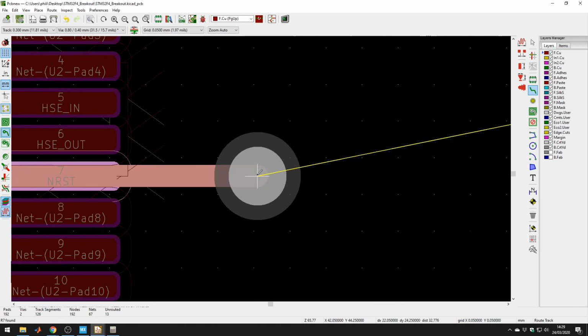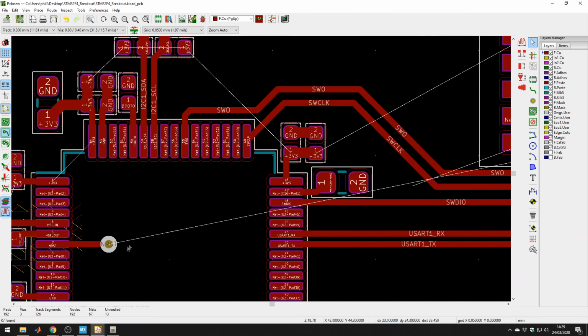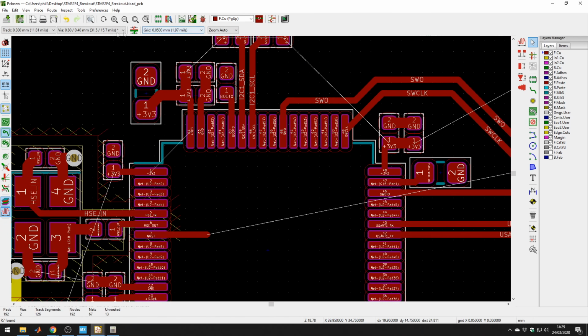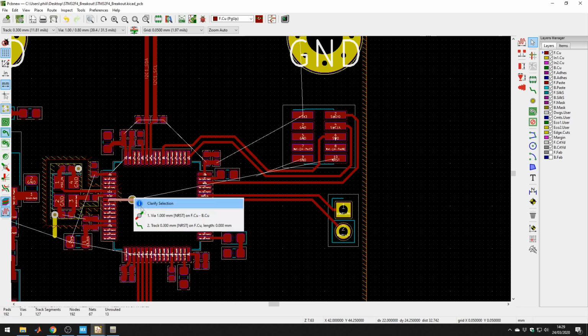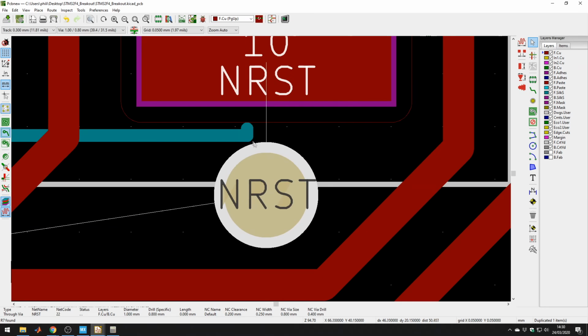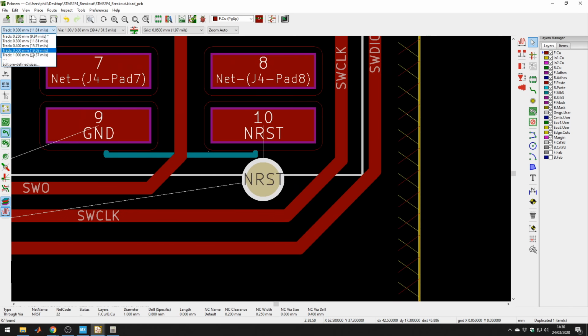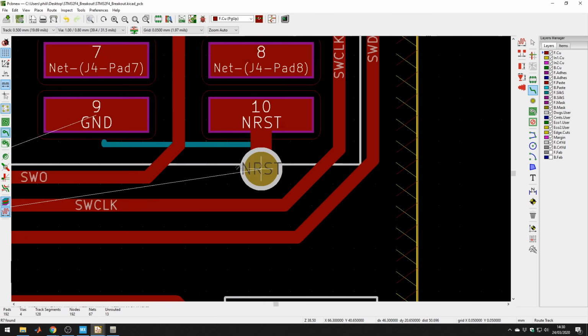Here, and press V to place a via. Now, because we have space here, let's delete that via and actually use a bigger one. Let's use that one. Might as well. Will we be able to fit one there, though, is the question. Yeah, that's fine. So, note on vias and drills, you don't want vias on the silkscreen because of course you can't print on a hole. So, make sure they're far enough away from silkscreen so you can still print.